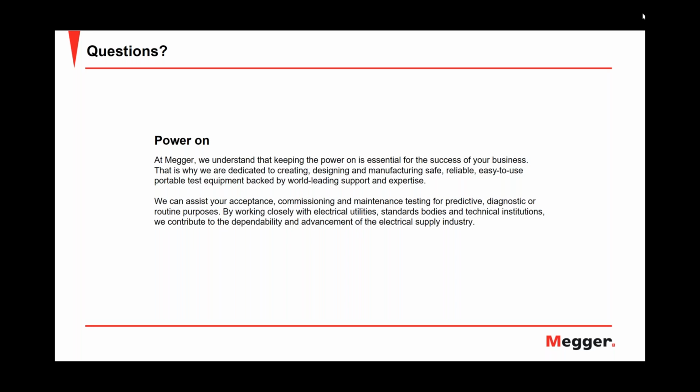Henning just explained the cable test, the withstand, as it is heavily regulated in various standards. But in fault location, in the most simple fashion, you have a small cable fault location system with you, maybe one of these micro thumpers, and that has multiple fault location methods, and its source is a DC source. So you have to do this first step as a breakdown test with the DC source.